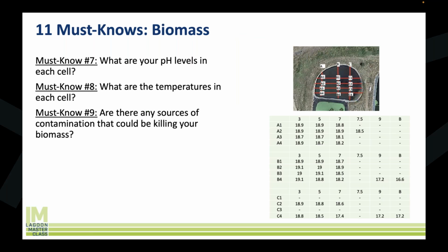And in the process of cleaning that equipment, they were using a chemical disinfectant that had what's called quats, quaternary amines, in it, which is literally a disinfectant in the sense that it kills bugs, and specifically it impacts nitrifiers, right? The specific thing they did the upgrade to solve. Nitrifiers are more finicky than other bugs, so they tend to be the ones that have the problem first if there's a problem. And it was killing their bugs, and they weren't able to nitrify, and they were busting their permit. They're coming to us and saying, hey, why doesn't our system work? And we found out that they had these quats coming from this industrial process.